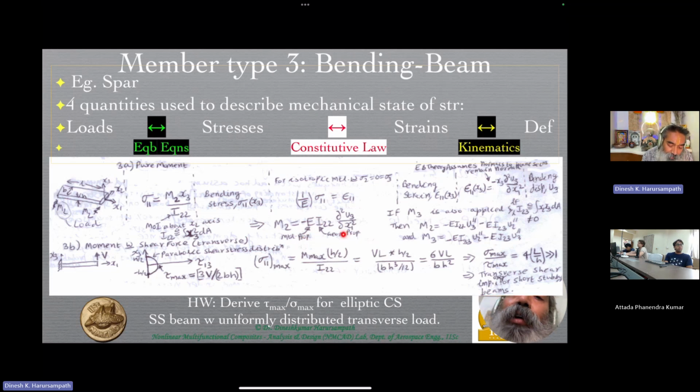There we had the area of cross section. Here we have a moment of inertia, particularly the second moment of inertia about the x2 axis, which is defined here as the integral of x3 squared dA, an area integral, so it's a double integral. Once again, you can play around with either the material for larger E values, or with the cross-sectional shape with the same area.